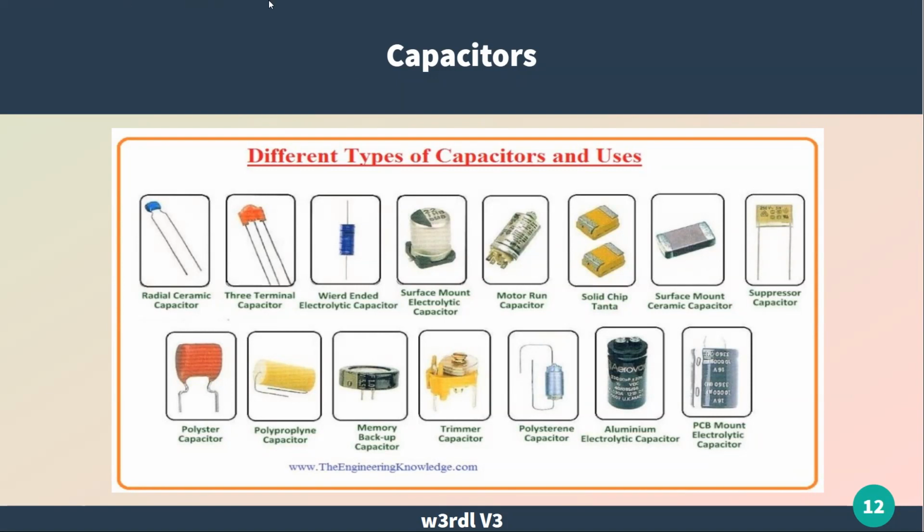Yeah. Looking at big electrolytic capacitors, a good reminder, I'll put my safety hat on. They are something that you can have unplugged for some time and still get knocked on your butt with the amount of current in them. Oh, yeah. Old TVs were really a biggie for that.